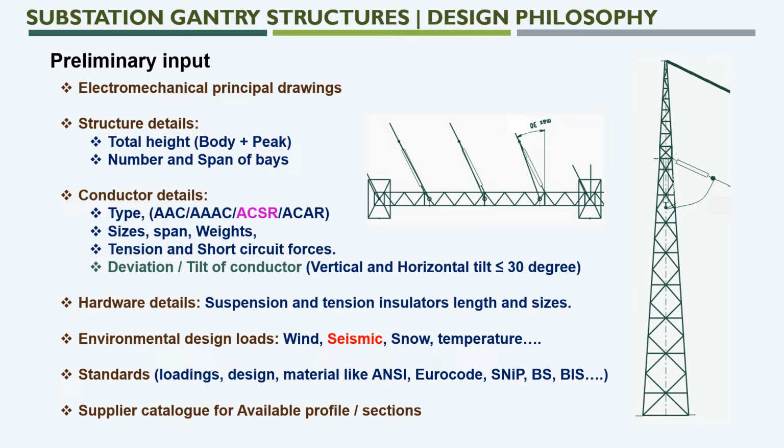Say for example, Indonesia used to have heavy wind loads, and Philippines also used to have more wind, cyclonic or seismic load. So in that case we need to consider the domestic standards, and for the design material we can follow global standards like ANSI, Eurocode or Russian standards.